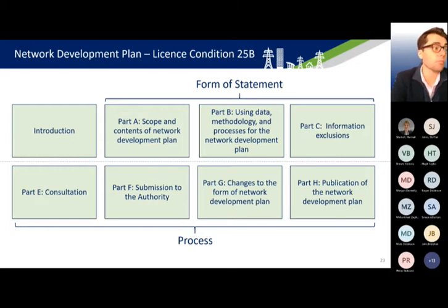They need to cover the 5 to 10 year ahead period, which follows on from the LTDS that covers 0 to 5 years. They need to report the network development requirements for new generation and load, and highlight areas suitable for new connections and flexibility services, using a best view of development covering all voltages down to 11 kV inclusive. And it needs to include a methodology document informing the user of underlying data and assumptions.